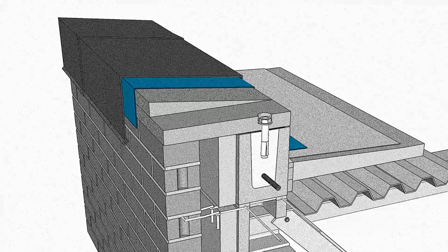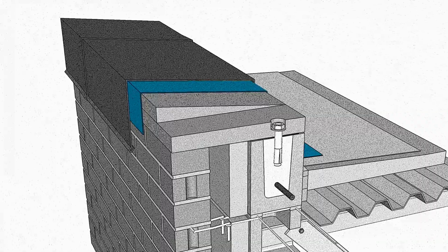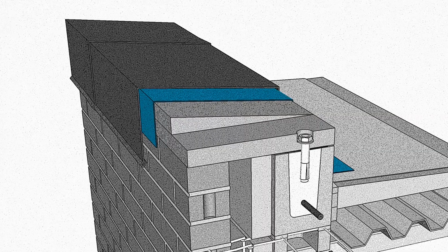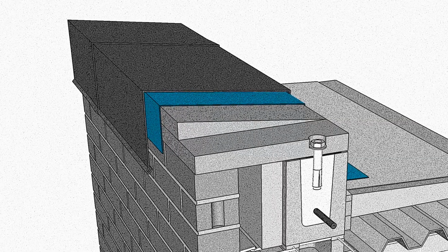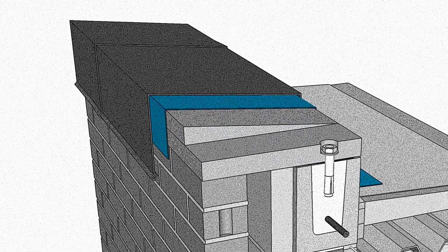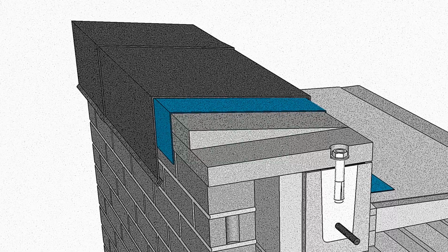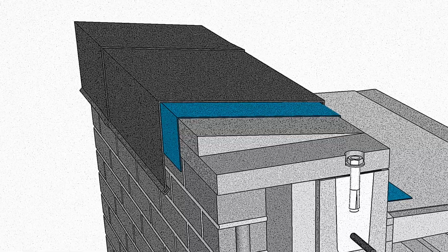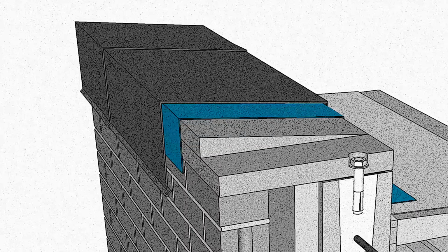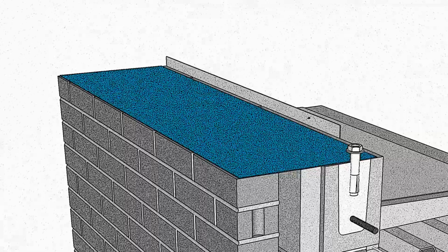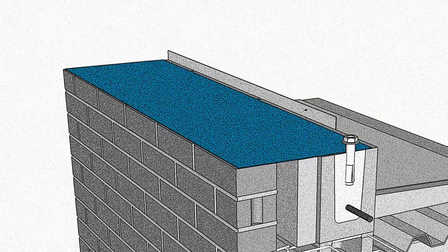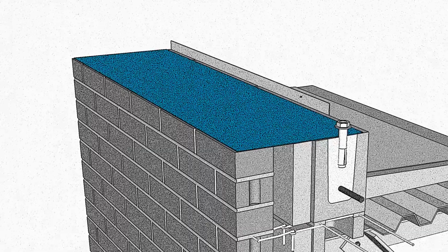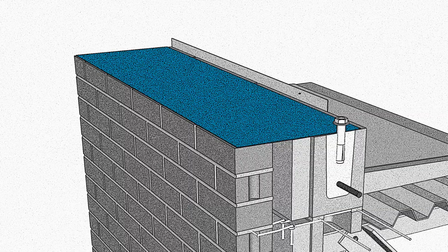In the case of wood blocking and metal coping, it is best practice for the mason to seal the top of the wall with flexible flashing material, secured with adhesive recommended by the flashing manufacturer, as well as seal around anchor bolts and embeds. This membrane will provide protection to the top of the walls during construction. In particular, it protects the top of the wall, as required by code, prior to the installation of wood blocking and metal coping cap by other trades.